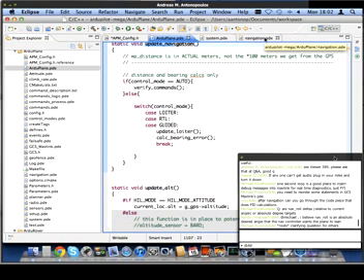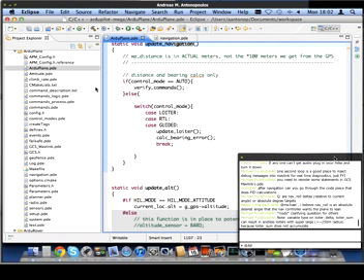It basically works out the bearing for the next waypoint, calculates what roll we want to achieve in order to move towards pointing at that bearing, and then it's up to the stabilization function to try to achieve that roll. And similarly with the pitch, it works out what our altitude is relative to our target altitude for the waypoint, and then it calculates what pitch we want to be at in order to try to move towards that altitude.